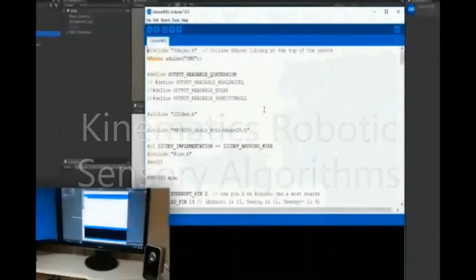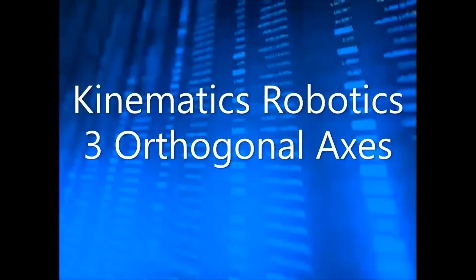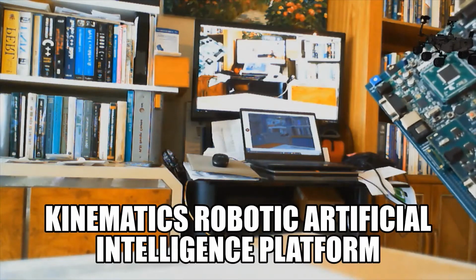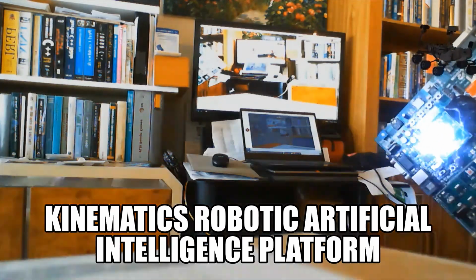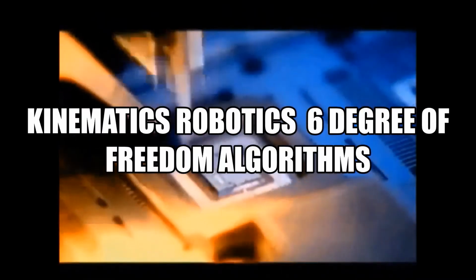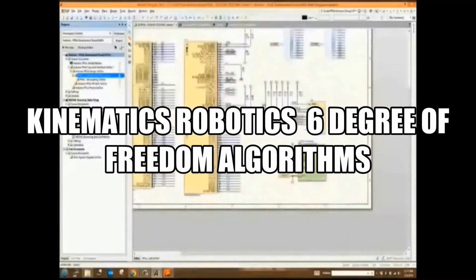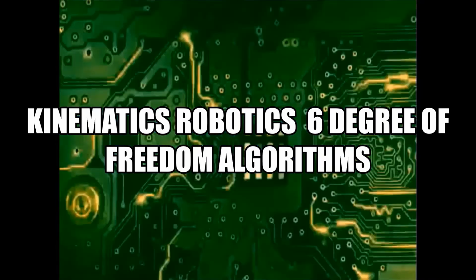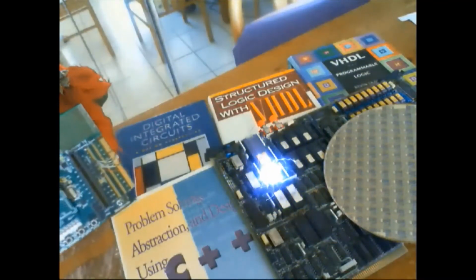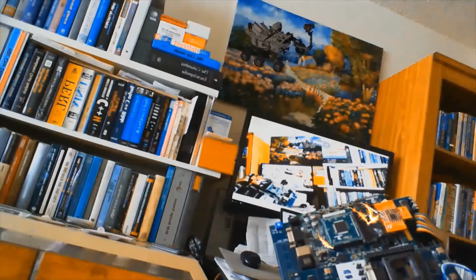The kinematics is solved in the sensor coordinate. Thus, simplification of the algorithms is done when approximations are used to solve the inverse kinematics. The kinematic method is based on the resolved motion rate control, in which the required velocity of the end effector is related to the joint variables. 6 joints are required in order to position and orient the end effector in space.